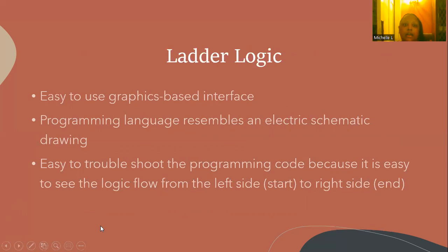Ladder logic, which is heavily used for PLC programming. It's a graphic user interface where the user can just drag and drop the graphic interface to help program the PLC. The programming language resembles an electric schematic drawing, where you can see where switches and relays are laid out on a schematic. That's what you would see in a ladder logic program. It's easy to troubleshoot the programming code because you can see the logic flow from left to right.